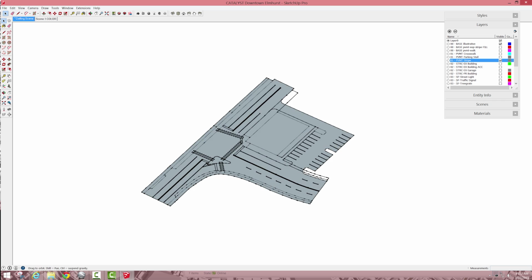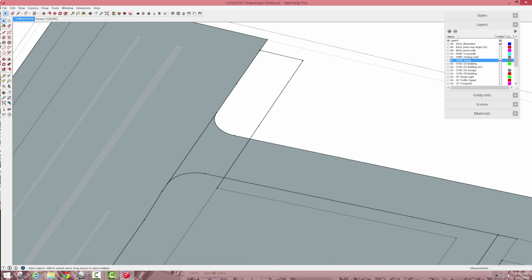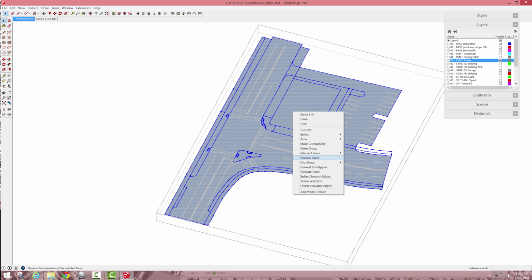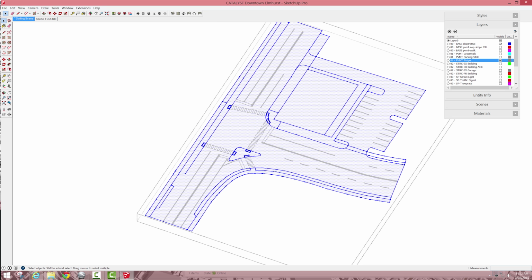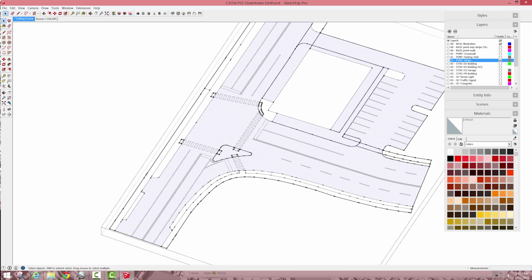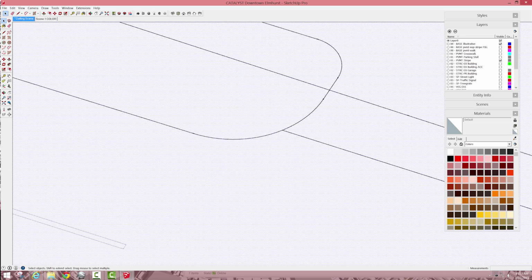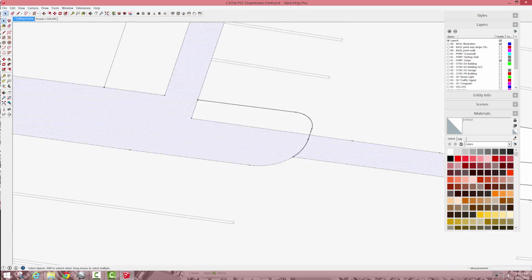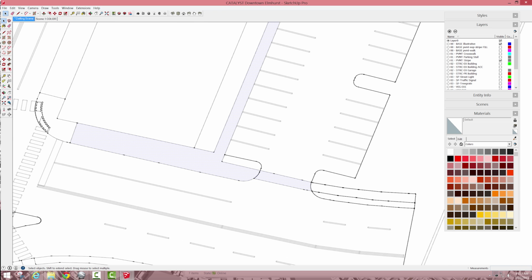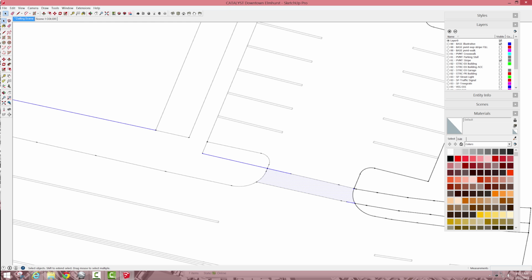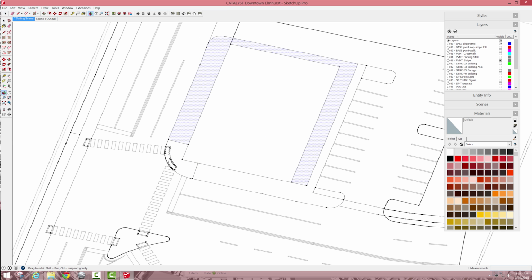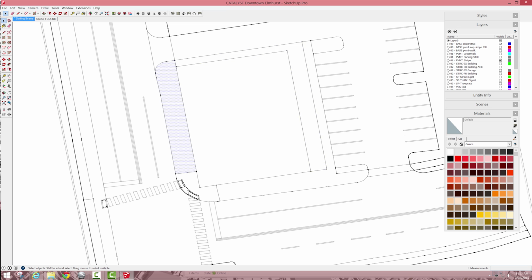All right, so that's essentially our view. Close off any weird areas. Okay, so that should be a good start. I'll even apply some colors now. They're very general because I know they'll change. Oh, there are some errors. Let's fix those. For whatever reason, this line's not dividing it, and they are coplanar. Everything on this is coplanar. So if you just do a cut and paste in place, sometimes it fixes the error. Do the same thing over here. So it did it again.